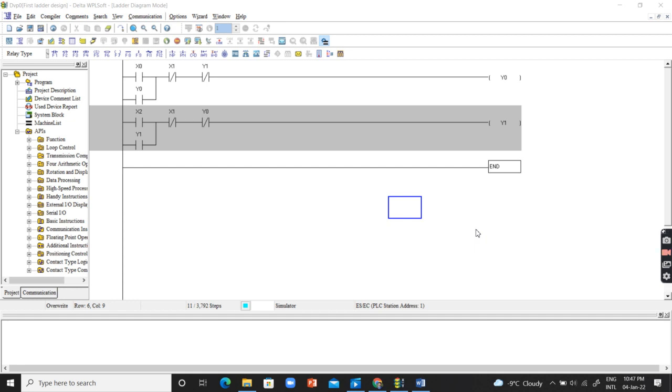So this is one of the applications of interlocking, so that it only allows the machine to perform certain behavior while restricting the other behavior. Over here, just to understand this logic, we have two outputs. Keeping in view the same application, we can say that this Y0 is my motor rotation in clockwise direction, and this Y1 is my motor rotation in anti-clockwise direction.